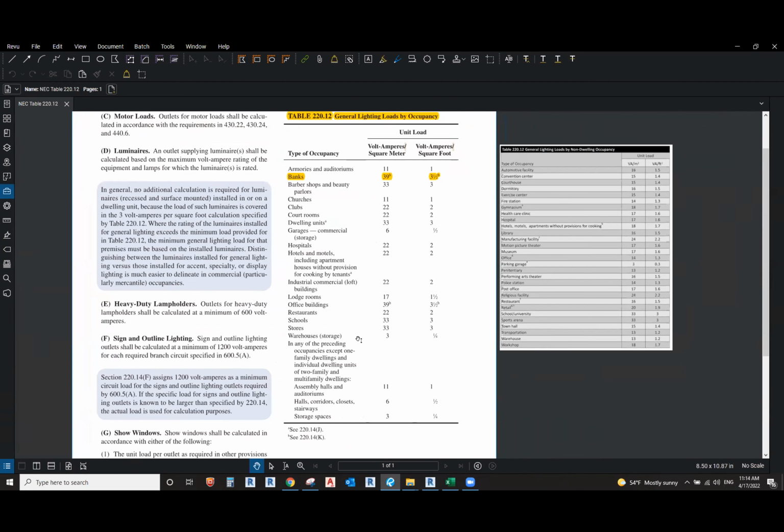So anyway, you have two types of calculation in your design. Since you already placed all your lighting, your connected load is based on the quantity of lighting which we already modeled in Revit, and that's connected. But according to this 3 kVA, we size the panel board, the cable, the feeders, and the main breakers. It means that your panel, feeder and breaker are more considered for the future also.